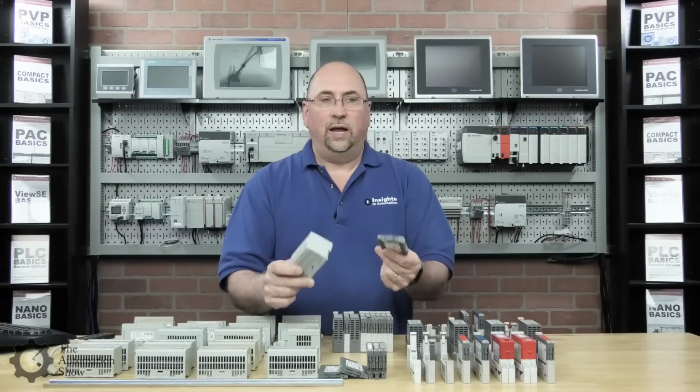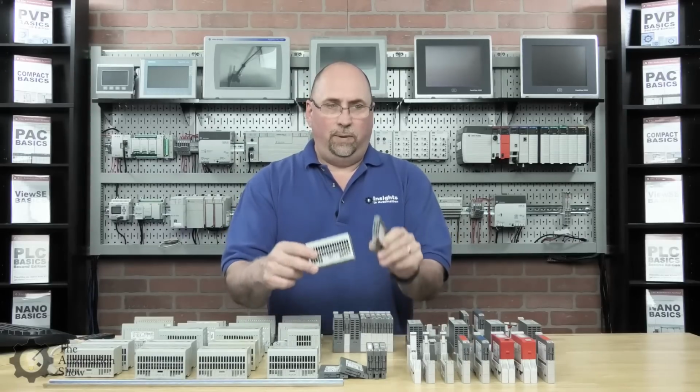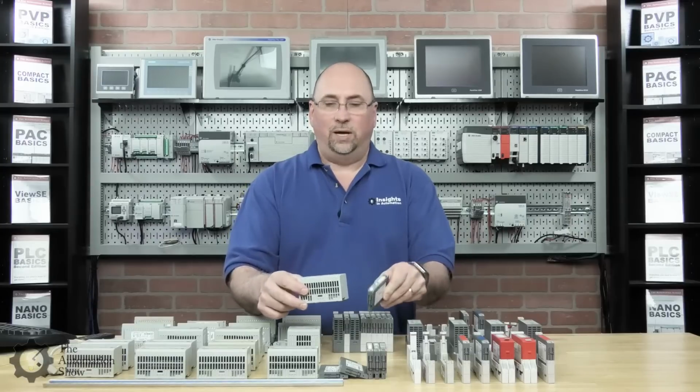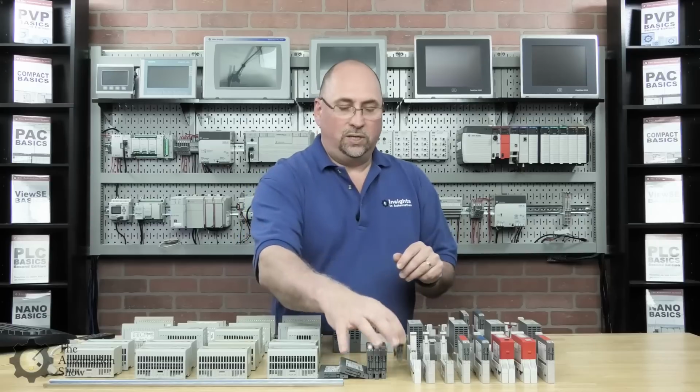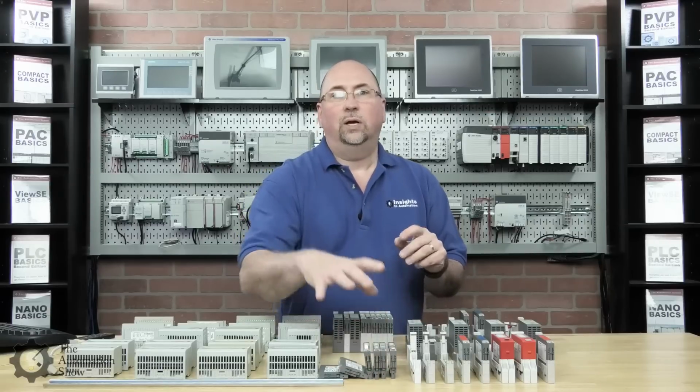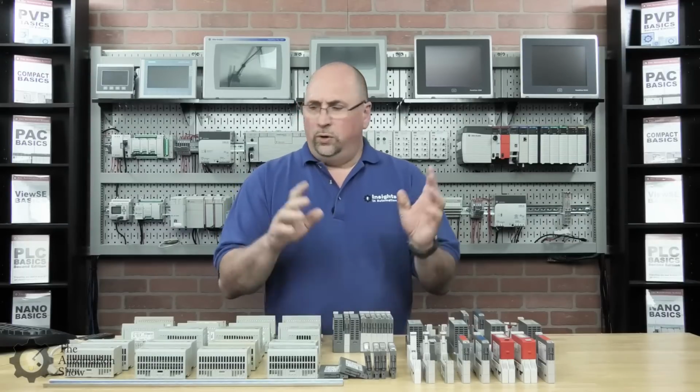So definitely not a hazardous location option. But on both lines, you can replace the module on the fly while the system is powered. And you'll see on the back of the modules, the pins are offset. The power pins are offset to enable that. What else? Well, you can split